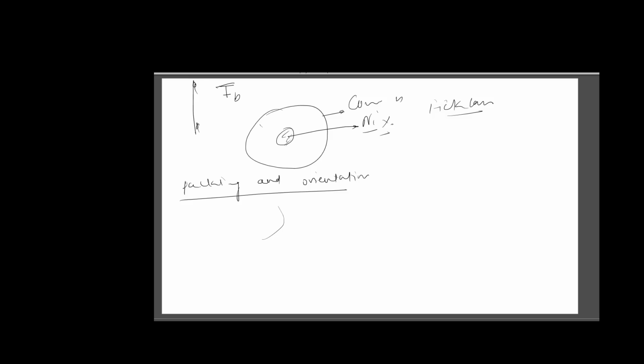And the moment the temperature of the sample goes slightly below the solidus line, these solidification fronts will fuse together and the entire material converts into the solid phase.